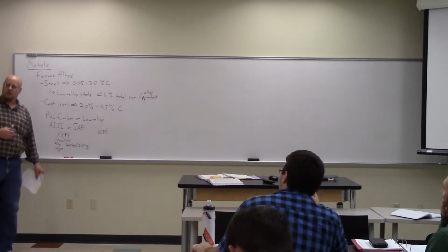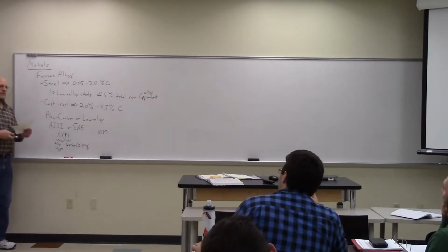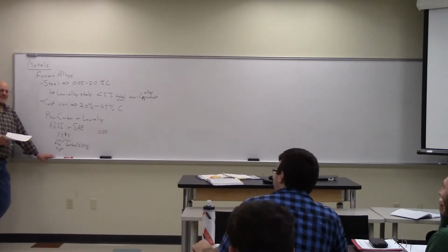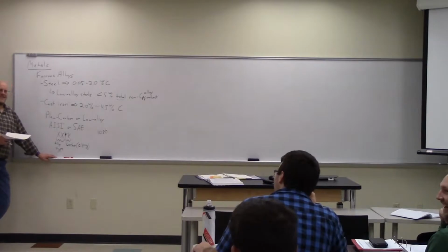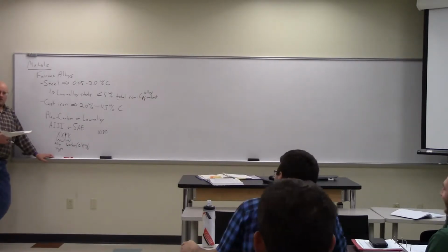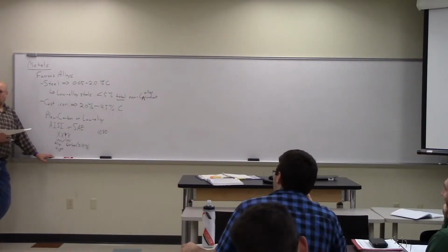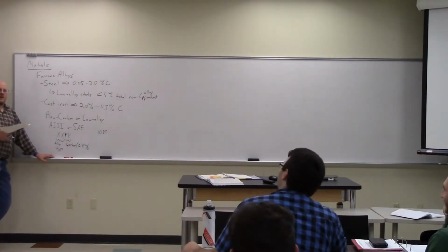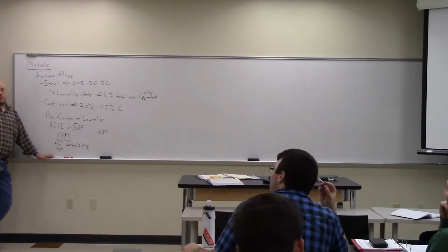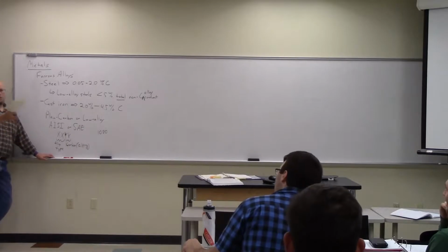What would we call a 1080 steel? Anybody? We'd probably call it a eutectoid steel, because the eutectoid composition is 0.77 weight% carbon. So 1080 steel would be a eutectoid steel. Actually, 1077 would be the eutectoid steel, but 1080 is close.